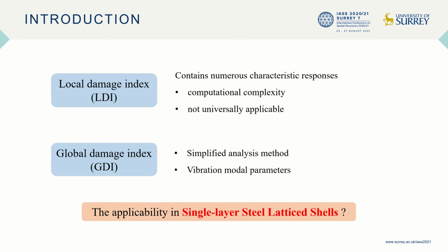Numerous damage indices, including local damage indices and global damage indices, have been proposed in recent years. The local damage index usually is strongly case-dependent and not universally applicable to spatial structures. The most widely used global damage index is the modal vibrational information of the structure. Considering that spatial structures work in a more complex three-dimensional way, the applicability of the traditional global damage index in such structures needs further verification.